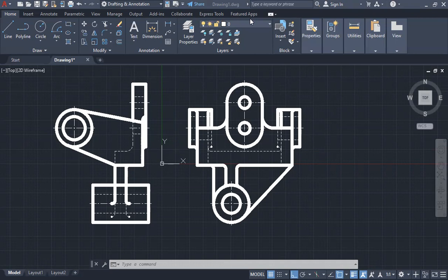Yeah, all of the basic principles for dimensioning we covered last week. So that includes dimension break, dimension spacing, as well as doing the different dimension tools. So like for this one, we have the aligned dimension style, the linear dimension styles, the radius dimension style. And yes, the dimension styles that we have.